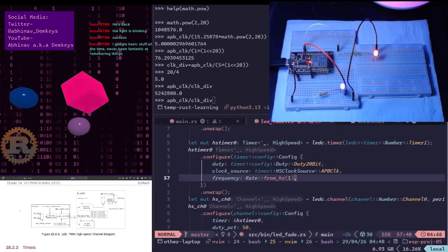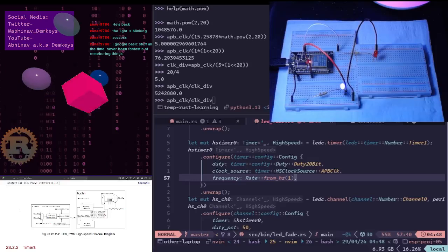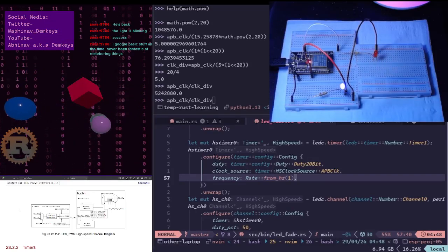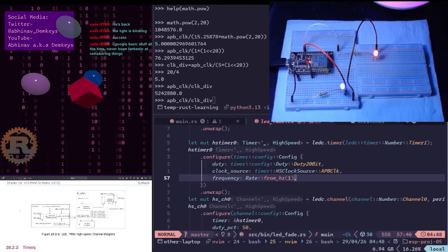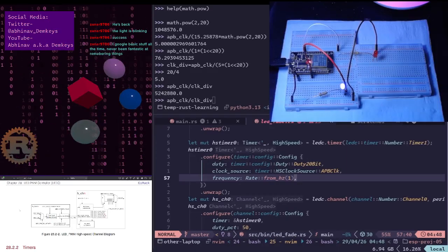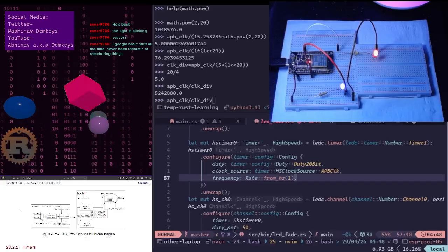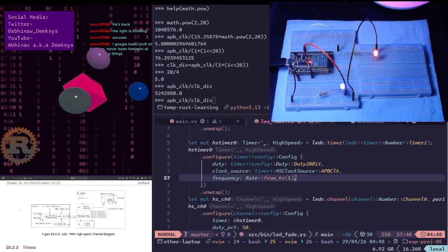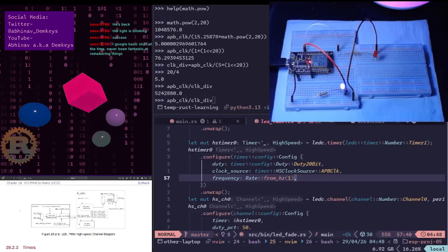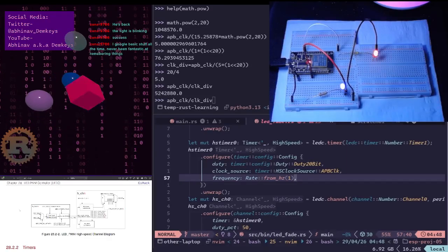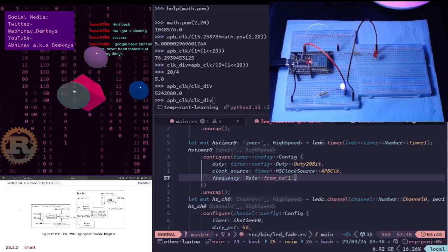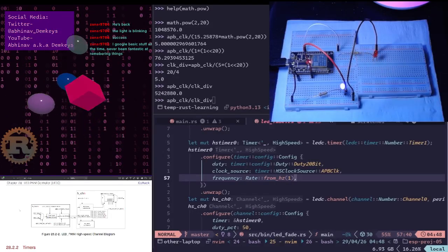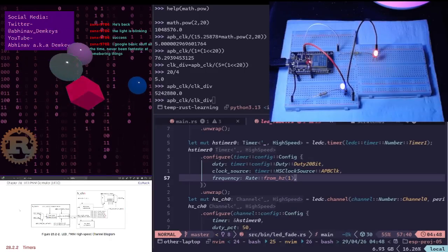So, carrying on with what Gemini said. Where was I? Okay, to answer your first question, in the ESP32 TRM, you should look at the LEDC or MCPWM chapters, specifically the architecture and register summary sections. The LEDC divider is often described as a fractional divider, which is where things get interesting.